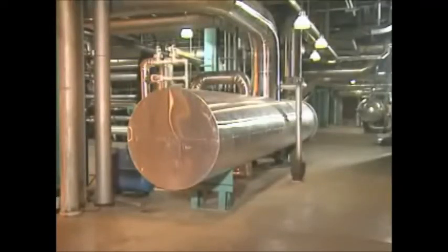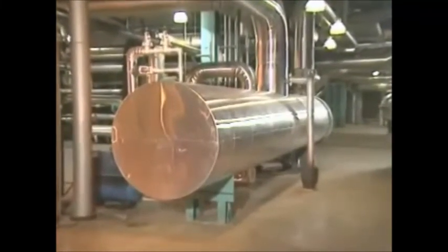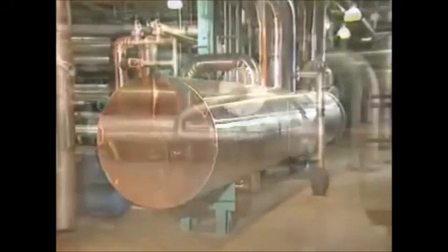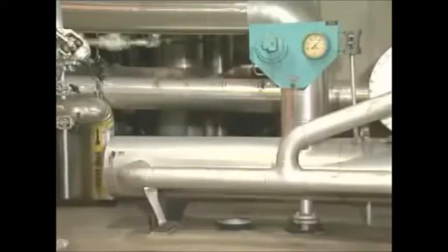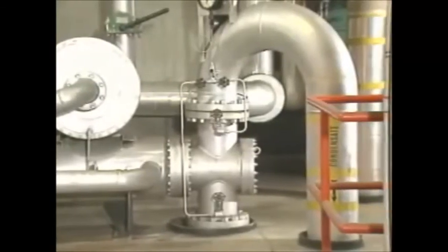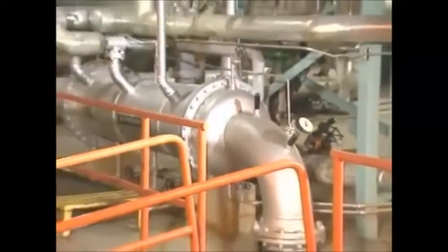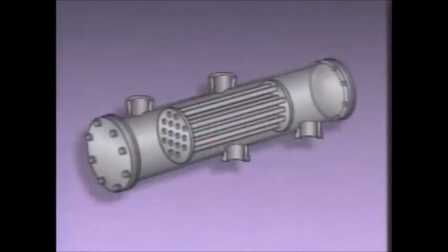A condensate and feed water system also has several condensers and heaters. Most of these are some type of shell and tube heat exchanger. For example, the initial warming of the condensate from the hot well is achieved by using the condensate as the cooling fluid in condensers. Gland steam condensers recover heat from the steam used in the plant's gland steam system. Air ejector condensers recover heat from the steam in the main condenser's air removal system. Both of these types of condensers are usually shell and tube heat exchangers.